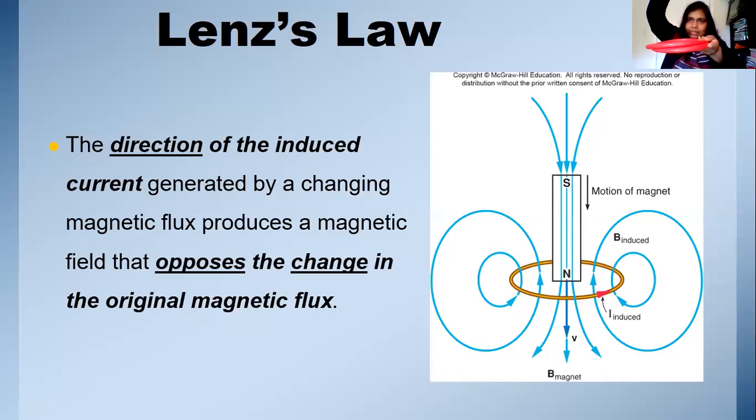All right. So let's say this is the coil, and here's a magnet with the north pole down. The coil will see a north pole coming downward. This is the direction of the magnetic field coming from the magnet. Now, this coil doesn't like that, so the coil will try to create a magnetic field facing north, upward, to avoid that effect. Again, use your thumb to indicate the induced magnetic field. So the magnetic field is going upward.